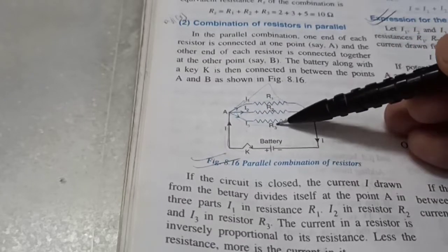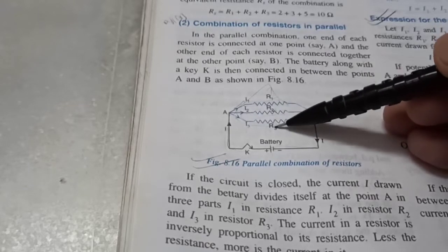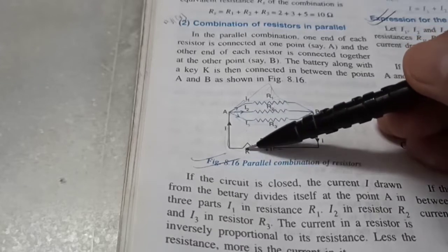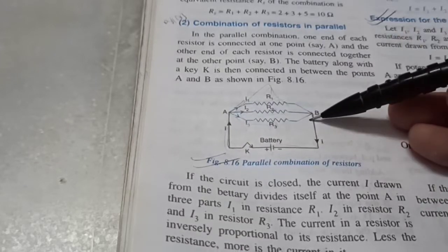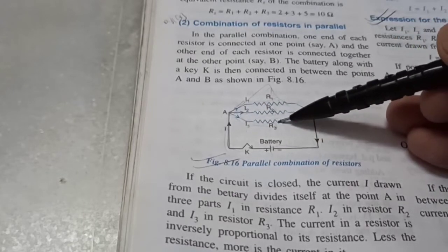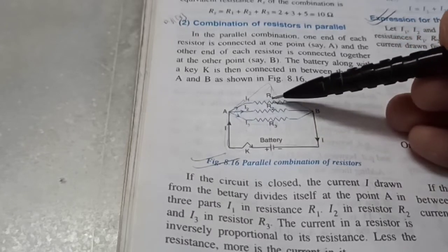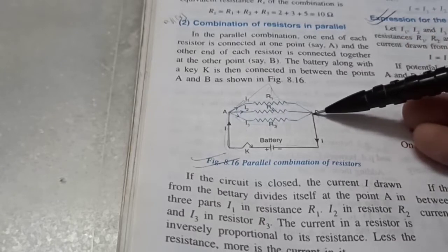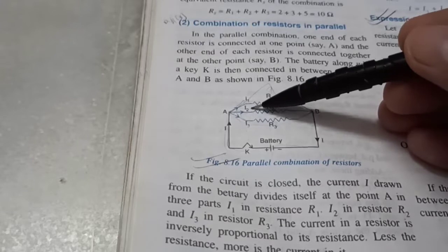So whichever has the highest resistance, let's say 2 ohm, 3 ohm and 5 ohm, whichever has the highest resistance will have the least current flowing through it, which makes sense if you have many cars moving on a highway and there are 3 roads and they want to get to the same destination. If they realize that this particular path has the highest resistance, then the least number of cars will enter this road, and the one which has the least resistance will have maximum current flowing through it. So when we do numericals, we'll have to keep this in mind while calculating I1, I2 and I3.